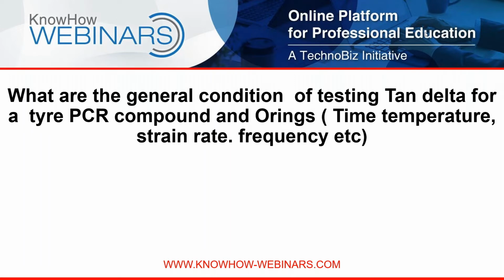But the broad way you should look at it is, first comes the application, then the service conditions, and from those service conditions, based upon your engineering judgment, you define the test parameters. Same for O-rings, it's an under the hood component, so mostly it's going to be in a static condition its whole life. The force is going to decay, the material is going to set, and that's how leaks would happen. So that is what you would characterize the material for. So that would be my answer for question number 4.